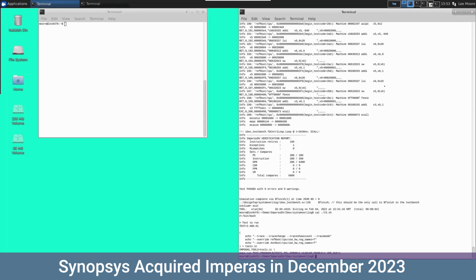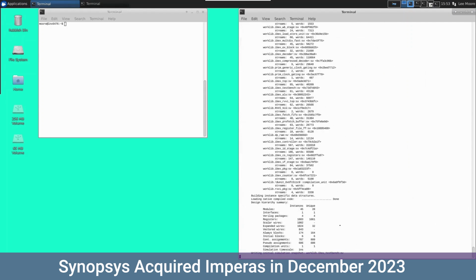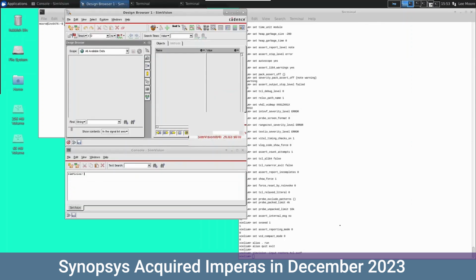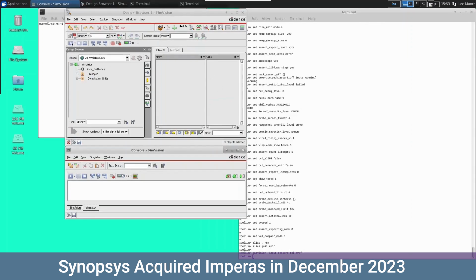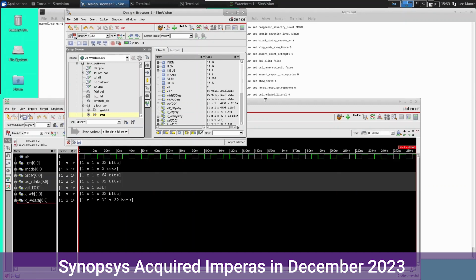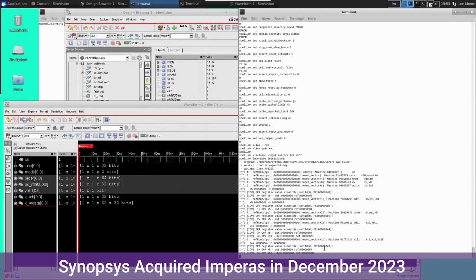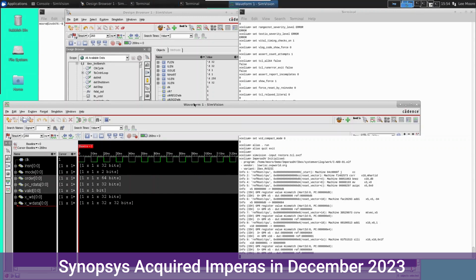So again, I've got a script set up here. What this is going to do is run up a Verilog waveform viewer, and we can take a look at the content of the RVVI interface that is being driven from our model, from the RTL model, that is. I've already pre-selected some of the signals here to make this a bit quicker as far as demonstration is concerned. But the important thing to note is I've gone back to the point where we've got the bug inserted in the RTL, and so we see after 5 miscompares that we're going to perform a finish of the simulation at this point.